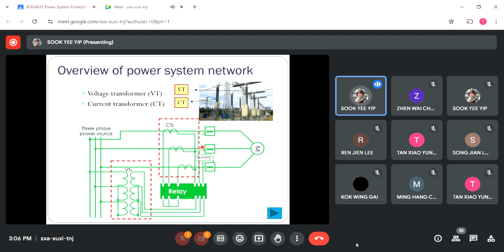And the other terminals here will connect to a common neutral point. That is the Y-connected current transformer. So how about the voltage transformers measuring the three-phase voltage, in terms of connections? It is also in Y connections as well, connected in parallel to the voltage source.